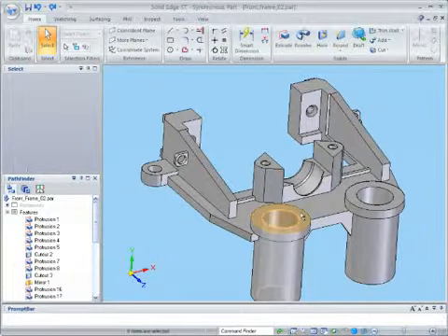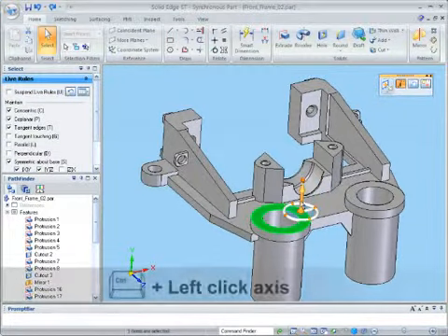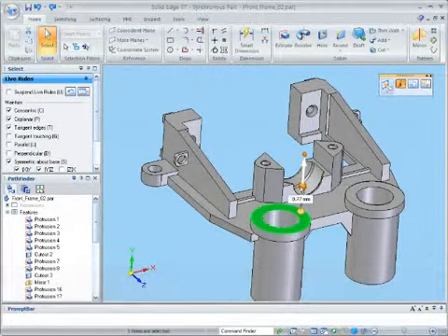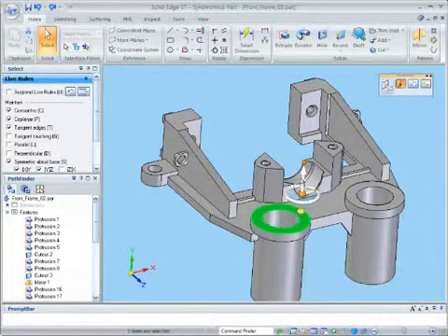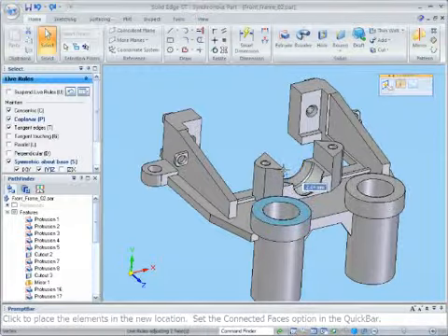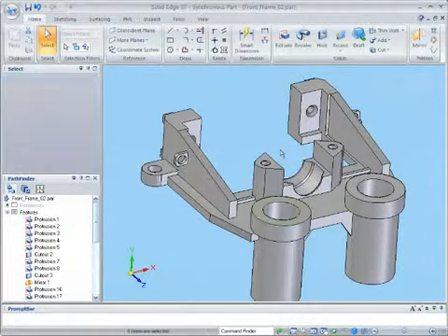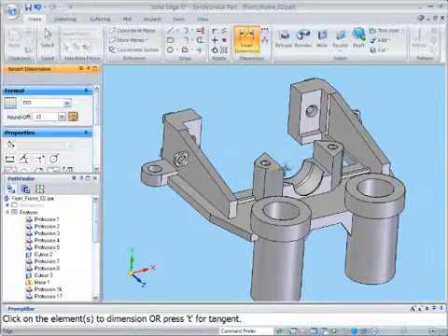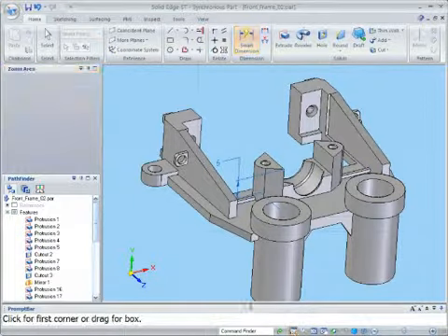Finally, this is how the steering wheel is used to move geometry to a set distance from other geometry or reference point. First, the steering wheel is indexed a set distance from the face being moved. Then shift-click the primary axis and use the Tab key to set the focus to the dimension box. Key in 6mm and click to accept. Now select the primary axis and drag it to the new key point on the reference geometry. I'll add a 3D dimension so you can see the new distance is in fact 6mm.